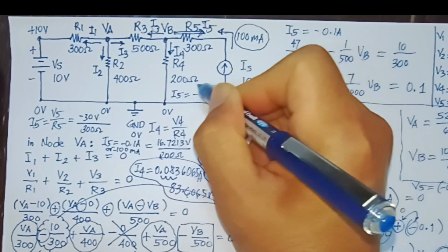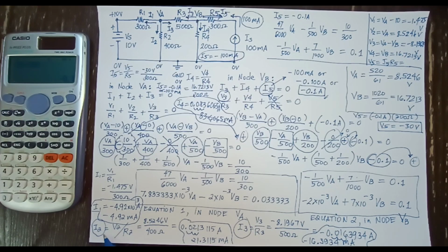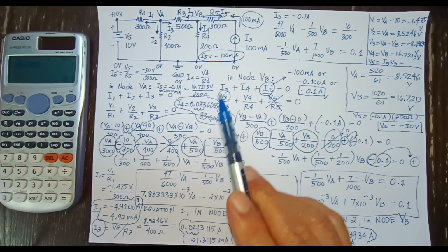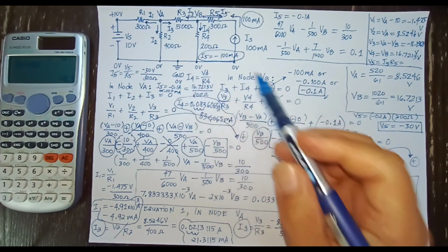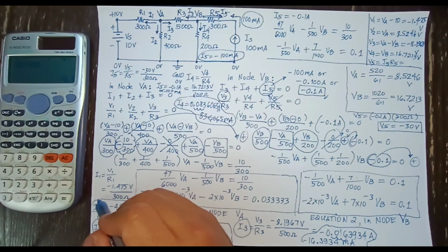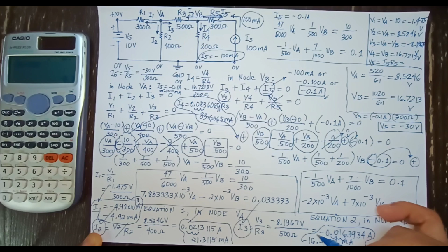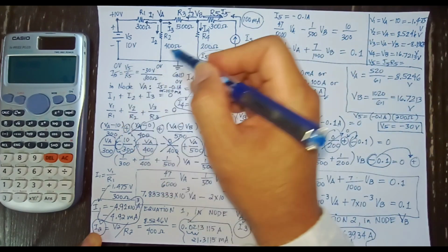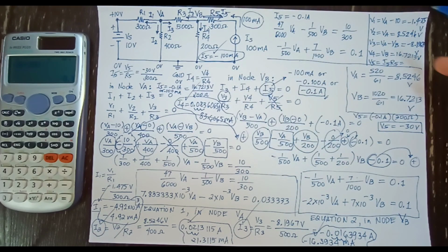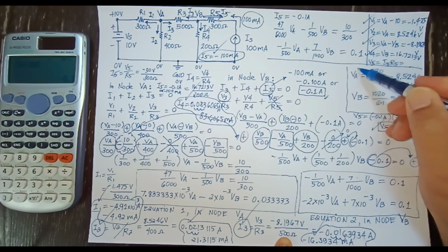And there you go. That's how to do nodal analysis and calculation of currents and voltages using nodal analysis. And this technique can be proven, if correct, if you do it in Multisim. And in our other video, I have shown how to do the circuit for this particular circuit with a voltage source and current source, and you may check and you will see that the values of my currents and voltages I have calculated will be equal to the measured values in Multisim.